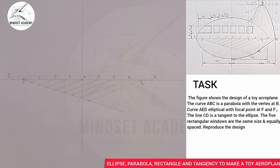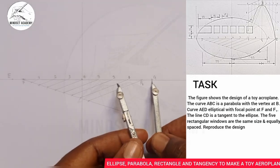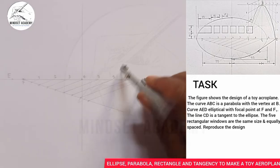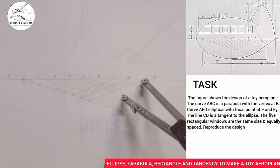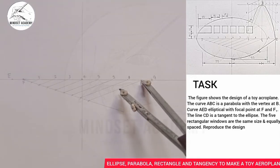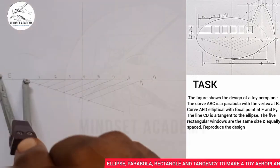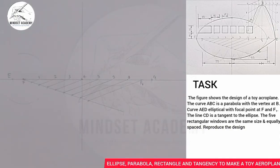The first step is from G to 1. Can you see that? I'll now put it on F1, and I'm going to strike an arc up, and also I'll strike an arc down. Can you see that? With the same measurements, I'll come to F. I'll do the same thing, strike an arc up, and also strike an arc down. Hope you can see that.